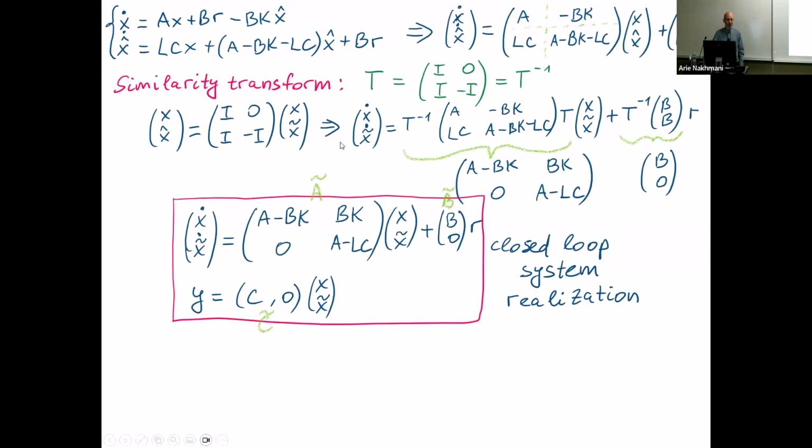Okay, so let's see what happens if we transform it that way. So you get from z vector to z vector. And pay attention that this inverse is the same as the original matrix. So it doesn't matter if I write here inverse, same matrix. So let's write x dot and x tilde dot now. Because if you remember, in open loop, without connecting the x estimated to the K, we had that just converging to zero, right? All of the exponents needed to converge to zero based on the A minus LC matrix. Everything was nice, but now it's connected to K and other things, so it could modify the observer itself somehow, maybe, but not really. And here's why.